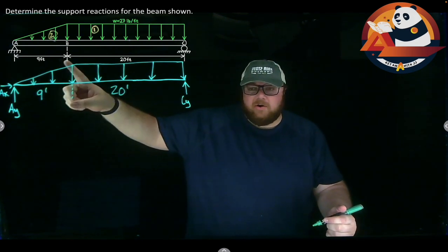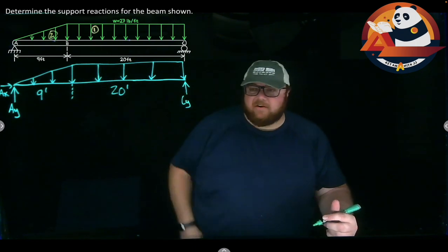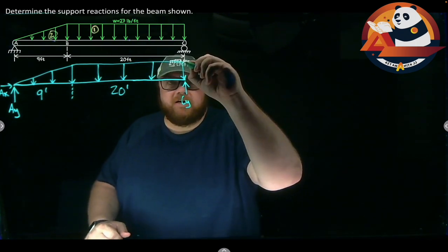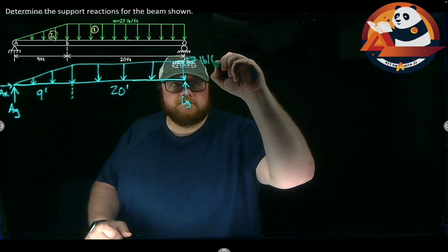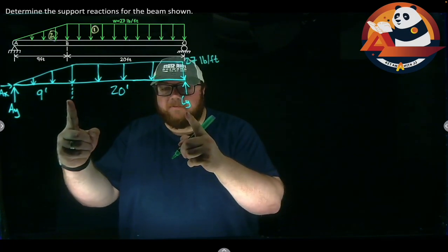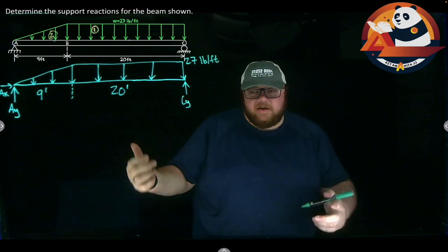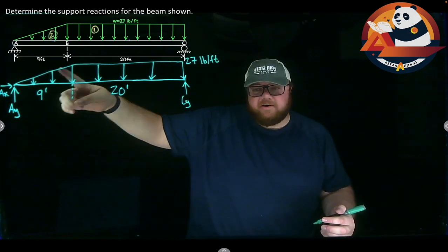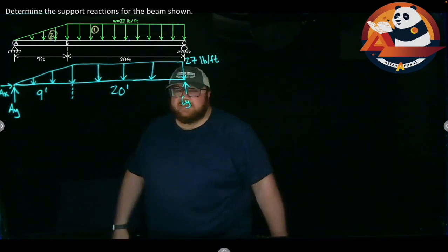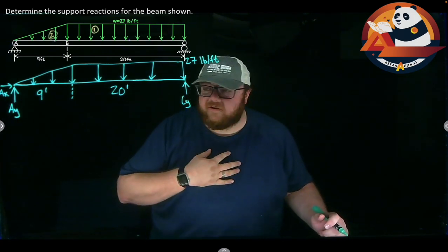I also know that the maximum height of the triangle, or the height of the entire rectangle, is W equals 27 pounds per foot. So in that rectangular portion, every foot that we go in adds another 27 pounds of force on here. In the triangular portion, we're linearly increasing from 0 up to 27. We can work with that. 3 unknowns, I can find all of them.